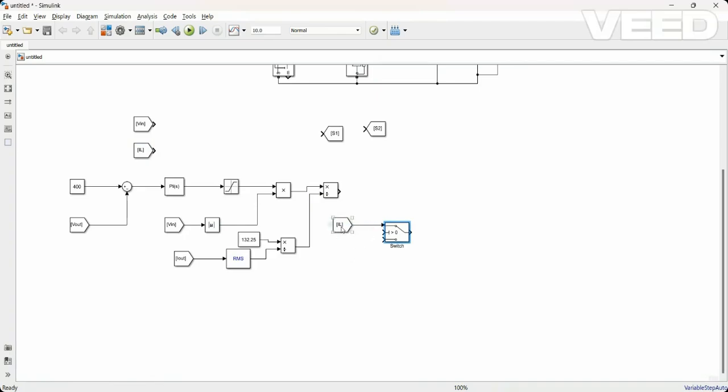When the IL is negative, we will multiply it with -1. So let's put a simple gain block with -1. Again, we are doing everything to ensure that the logic remains the same. It's just how we operate the switches that will change. In the second chapter of this course, we looked at when we are in the positive half cycle, which switches we switch on and how the current flow happens, and similarly in the negative half cycle. So this is what we are trying to build here.